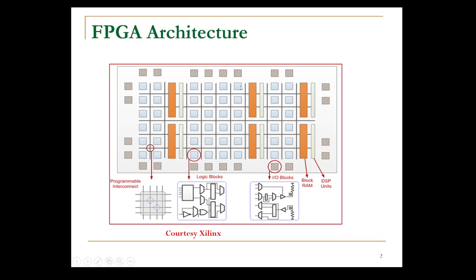Each cell in the array represents a CLB, configurable logic block, and these blocks have a multiplexer and different types of logic gates embedded in them. The point which connects the neighboring cells is called a programmable interconnect, and this also comprises many elements. So this is an FPGA architecture in an array format.